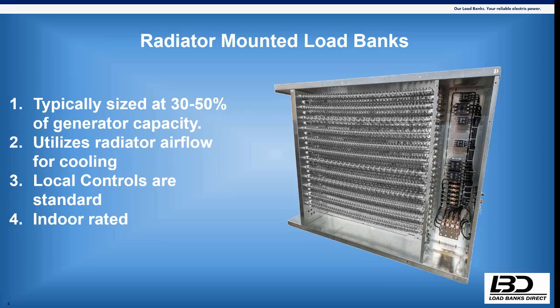Radiator mounted load banks are indoor rated when compared to a stationary load bank, because stationary load banks are typically installed on a concrete pad outdoors, as I mentioned. These are mounted on the face of the radiator, so they're going to be either inside of a custom enclosure typically, or on an open generator set. So they don't really require the outdoor rating.